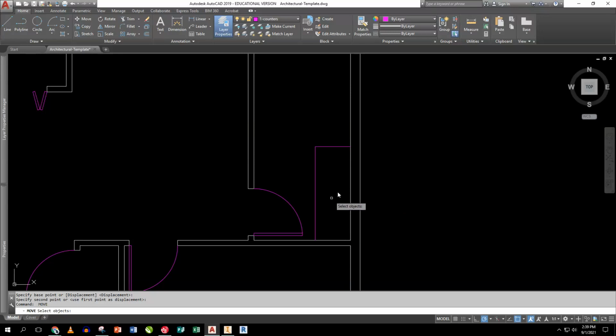You just have to put the basin in it now. So if you want to, you can actually move this out a little further and make it a 24-inch deep cabinet. But notice I left the gap there because I only went 22 with this. Well, I can use the fillet command with a 0 radius to just close that off. Now, I don't draw in the backsplash. I don't draw in the mirrors. That's it. Okay, I try to keep it simple.